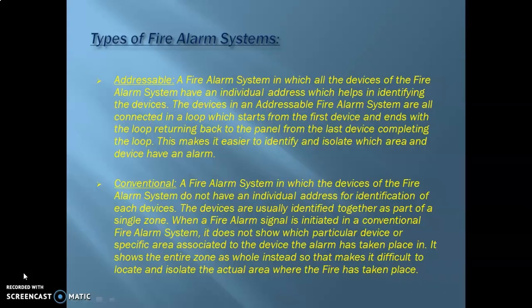But since the addressable fire alarm system is so flexible, owing to the fact that every device has its own address, it is more desirable for the design and installation of fire alarm systems in a large building, because it is a lot easier to divide the fire alarm system for a large building into different zones using different loops. So it's a lot easier using the addressable fire alarm system.